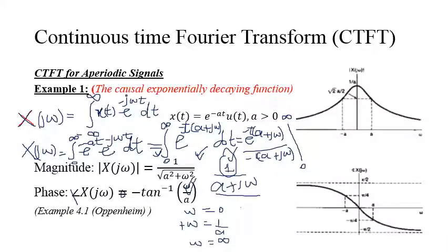Using these values, again omega equals 0 is the same, but you take omega equals, for example, minus 1 by a, and for the third case, omega equals minus infinity. Thus you take negative frequencies like here and positive frequencies here, and you find the magnitude response, and you also find the phase response. Remember that the independent variable will be omega, so you'll get a graph something like this.